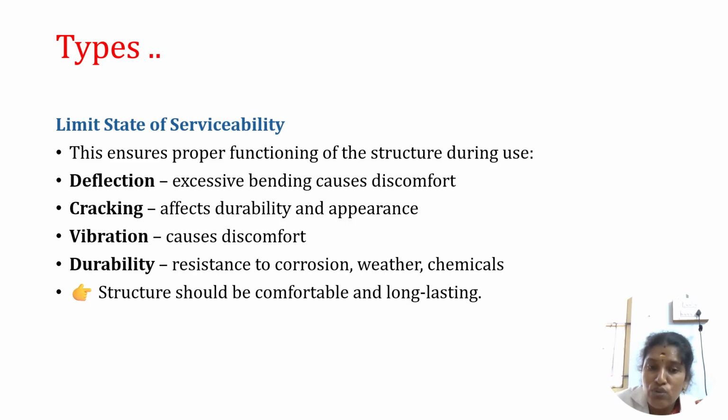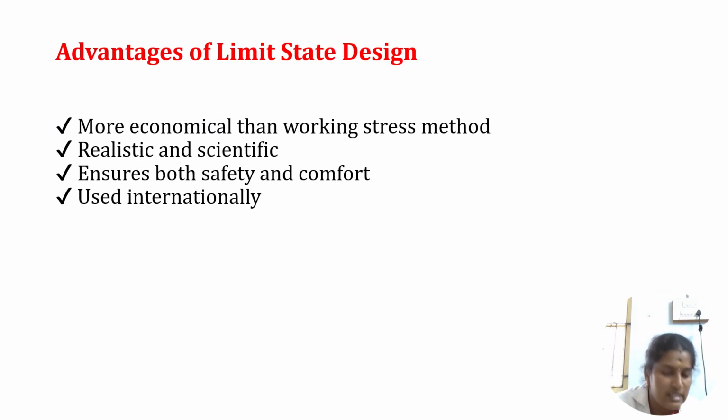So we can ensure this kind of structure will not collapse for any kind of reason. The main advantage of limit state design is that it is more economical than the working stress method. I told you the reason: they prefer the ultimate strength, right? It is realistic and scientific, ensures both safety as well as serviceability, that is called comfort, and it can be used internationally.